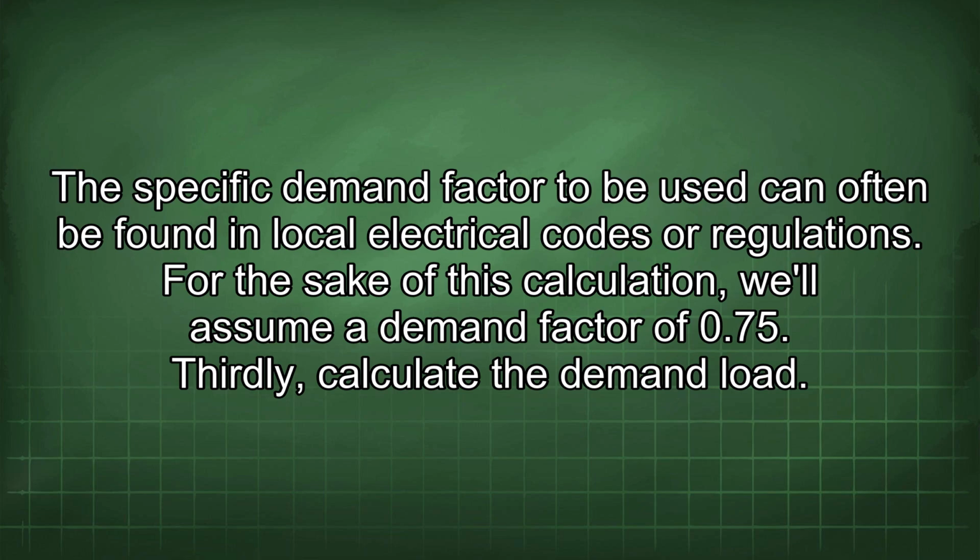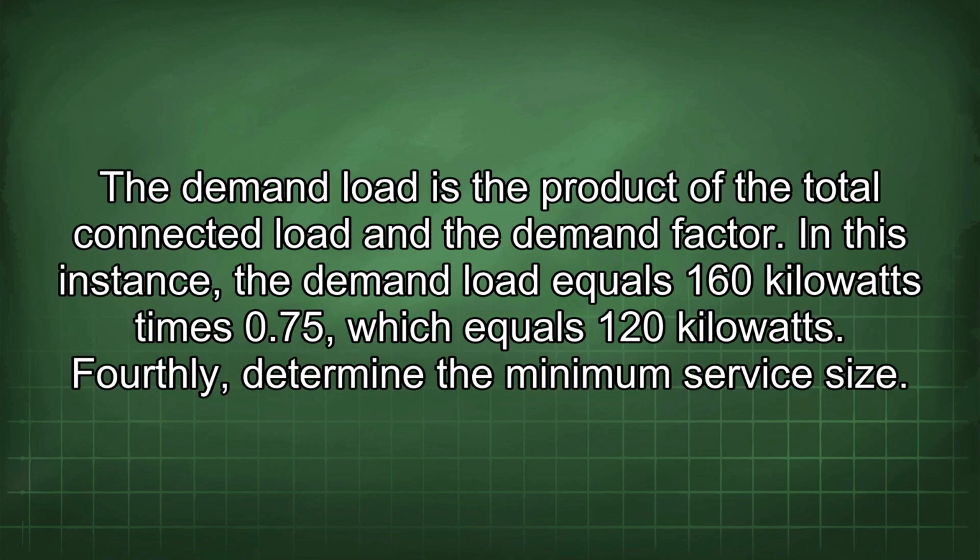Thirdly, calculate the demand load. The demand load is the product of the total connected load and the demand factor. In this instance, the demand load equals 160 kilowatts times 0.75, which equals 120 kilowatts.